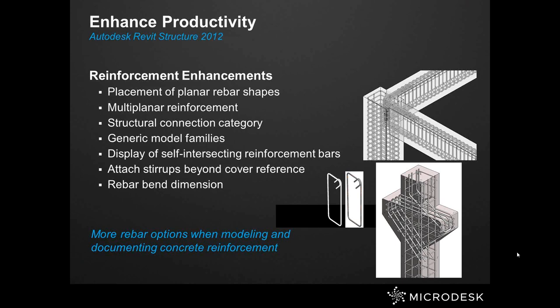Planar reinforcement is depicted more accurately in both 2D and 3D. These intersecting bars overlap as they should. The level of detail is maintained with the existing symbolic nature of rebar. Rebar stirrup and tie style families can be set to snap to the exterior of a cover reference rather than to the interior. These additional functionalities of reinforcement modeling and visualization help move us forward to the next stage for detailing and scheduling.